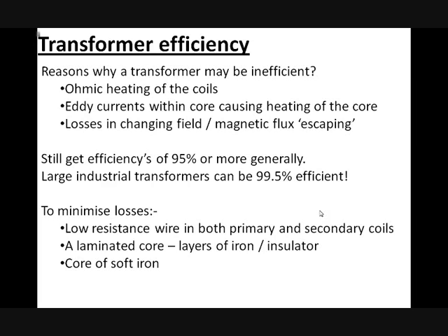But even with these 3 problems, we still get really high efficiencies. Even in the lab, you might get 90%, 95% or more. And large industrial transformers with cooling, oil-cooled, they can be up to 99.5% efficient, which is tremendous, really, if you think about that figure.